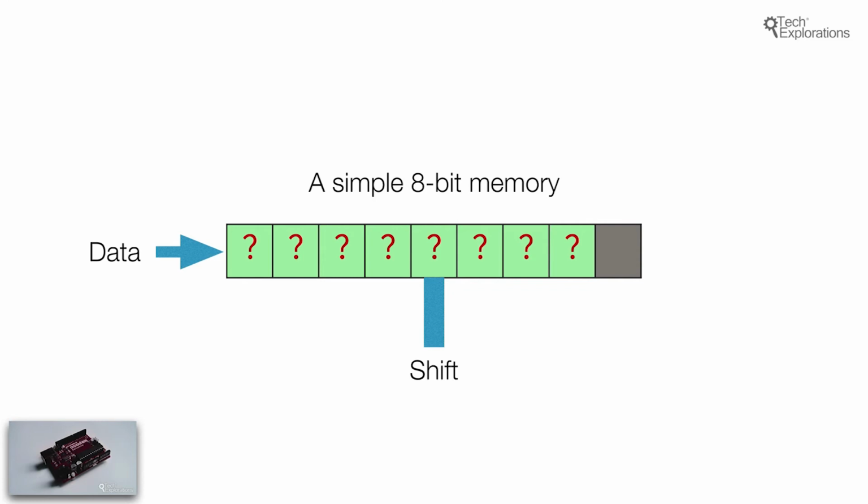Think of a shift register as a single byte memory. Each of the bits in this memory is connected to the outside world via a pin on the package of the chip that contains the memory. You use a single data pin from the Arduino to write each bit, one at a time. Because each bit is written individually and all bits can be read all at once, we say that shift registers are devices that support serial in and parallel out.